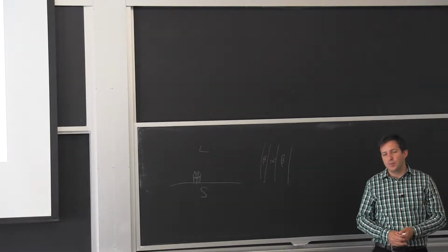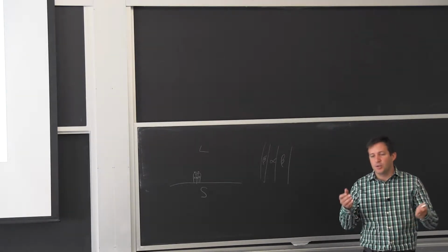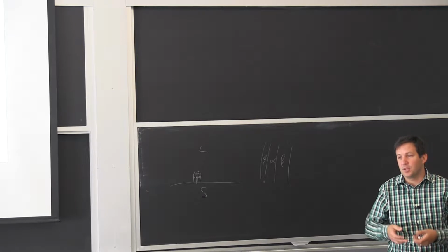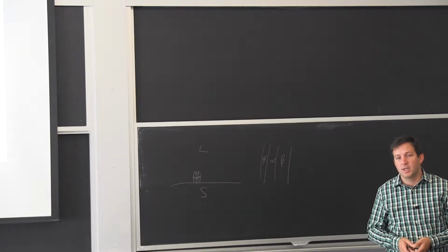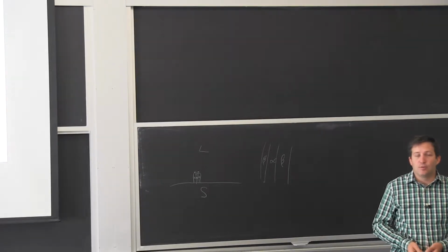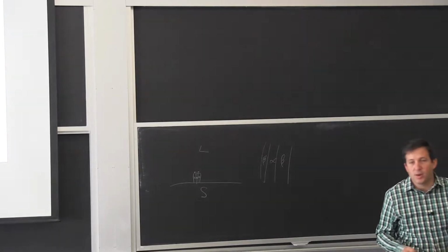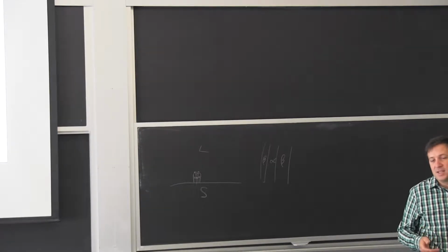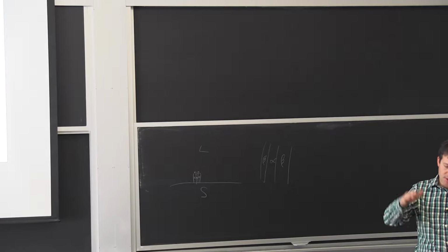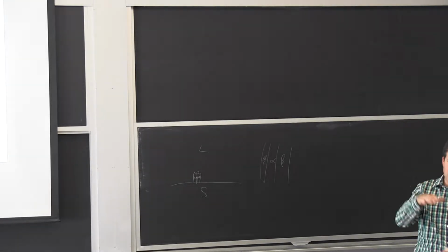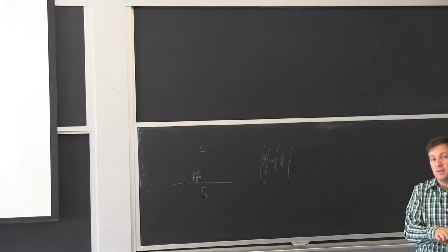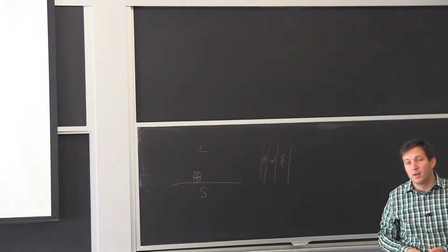What's important in the casting is to make sure that you don't collect too many inclusions, because these you can't really get rid of. You can just break them down and make them smaller. It's a problem with casting aluminum. So aluminum for aircraft tends to have a relatively low fracture toughness in the transverse direction, because as you go from the big billet down, you smooth down the inclusions, but they remain there and essentially kind of pre-crack.